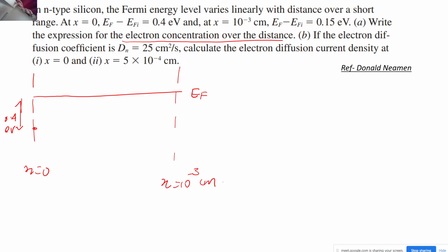mid gap. But then as you increase doping and you go to 10 power 17, 18, 19, it goes close to the edge of the conduction band, let's say if you have electron doping, right? So even though you have 8, 9 orders of change in the carrier concentrations, you'll have only a gradual movement across the band gap, right? So that's one significant point that I wanted you to note.